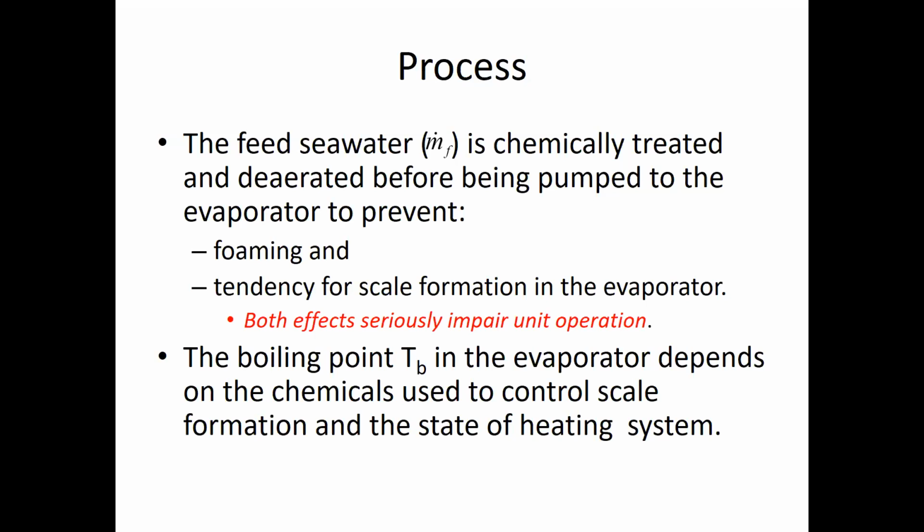It comes at a certain temperature and the salts start to precipitate. It is isolated from the seawater and it stays on the surface as crystals, as salts. And that's something that you need to avoid as much as possible. That's why you put some chemicals in the seawater before coming to the unit. And this is what we call pre-treatment.